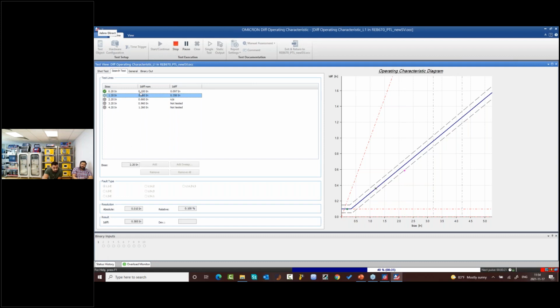Now you can see here the expected 1, I nominal, it becomes 0.097. Now it is 0.36, so it is 0.356, and it is within the tolerance, so it is fast. Now it is testing the third point. And how we are testing now, we are injecting in 2 feeders, one reference, B1 and B2. Yes, exactly. And you have to repeat this between 2 and 3, 3 and 4, and all of that, because that will take longer time. But with the relay sim test, one time you can inject all if you have enough number of CMCs to cover all feeders. So we can stop as you like.